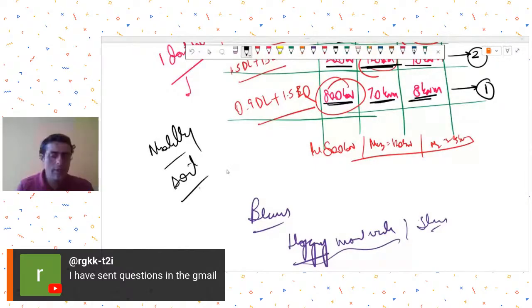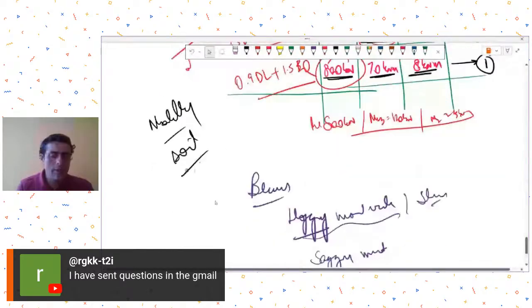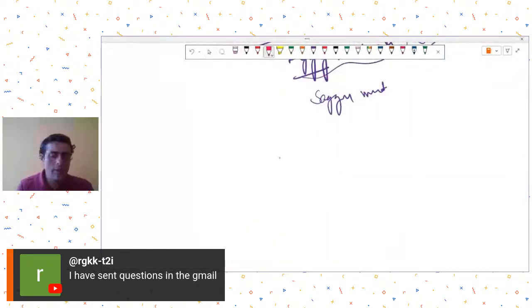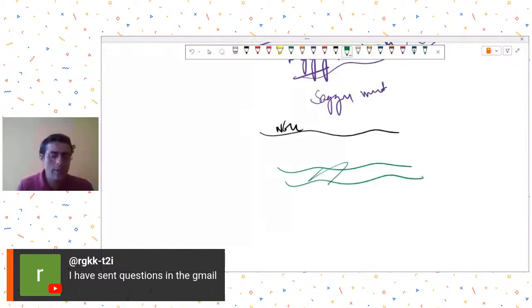Generally, what we do is if your soil has a tendency of liquefaction, then we generally try to take our foundation systems below it. So it might happen that let's say this is your NGL and there is a certain strata or a certain zone which is prone to liquefaction.